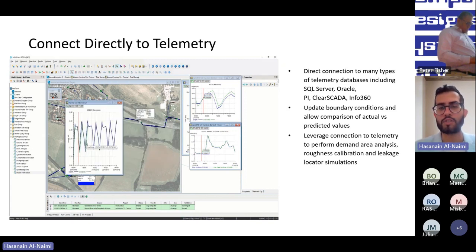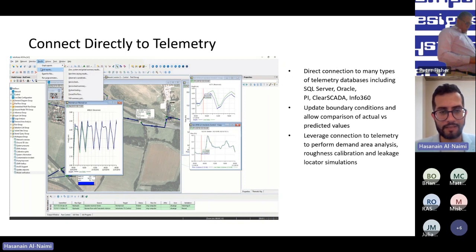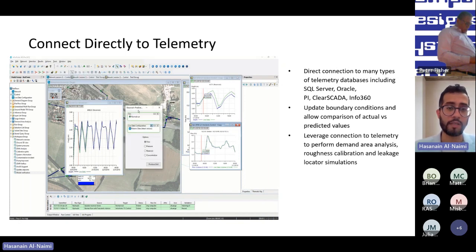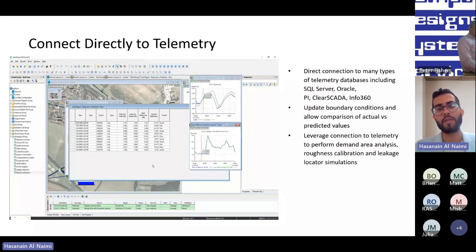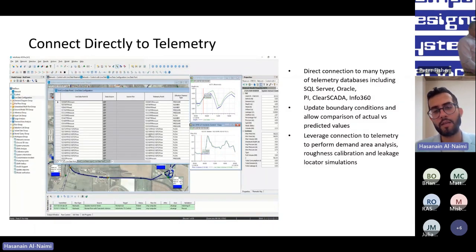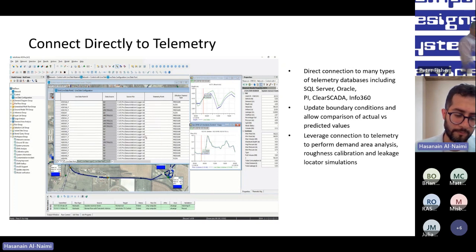Of course, the calibration process will become much more difficult if you don't have any data, right? But you can always do it. If you're looking at water quality, you can get some lab analysis on the water quality and calibrate your model to suit that starting point, that boundary condition. And then the product will do its mathematical modeling and will be able to track what's happening to the water quality in your pipes, in your systems, as you go further from the source.